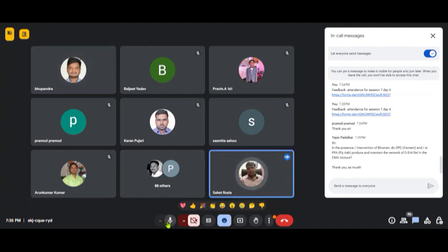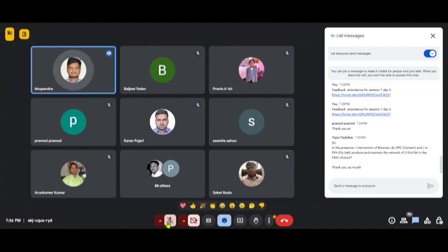There is one more question. Can we use other industrial waste ashes like rice husk ash as a filler? Yeah, definitely we can use them. Wherever you find that there are some cementitious properties present in any type of waste. We have also used not rice husk ash, but GGBFS, ground granulated blast furnace slag, because that also has some kind of binding properties. We have used it in the lab and found that it also improves the performance. So wherever you can find cementitious properties in ashes or any type of material, that can be used as a filler material in your cold mix asphalt.